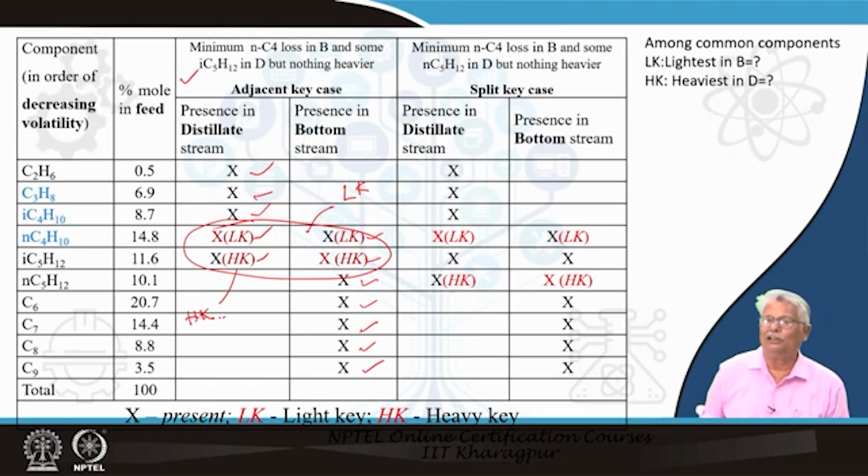So, can I say, or can you appreciate at this particular point, that the LPG, which is a distillate stream here, in the left case or case 1, is not going to contain any NC5, while in the right side case, case 2, it is going to contain this. So your LPG is going to be purer in the first case and relatively impure in the second case. Quite naturally, you have an extra yield of LPG volume of production in the second case.